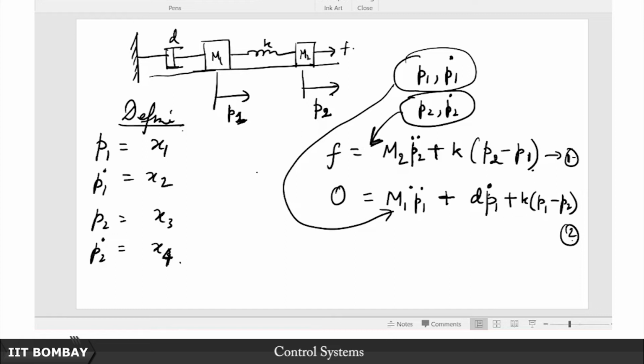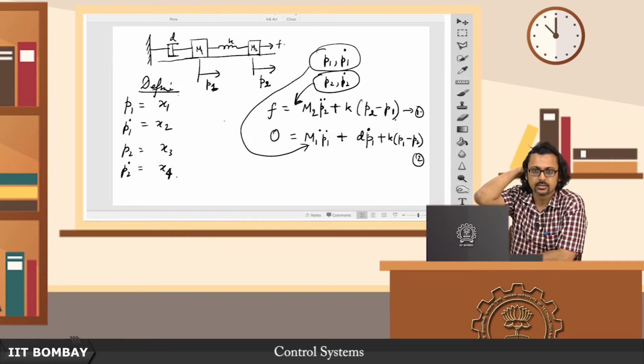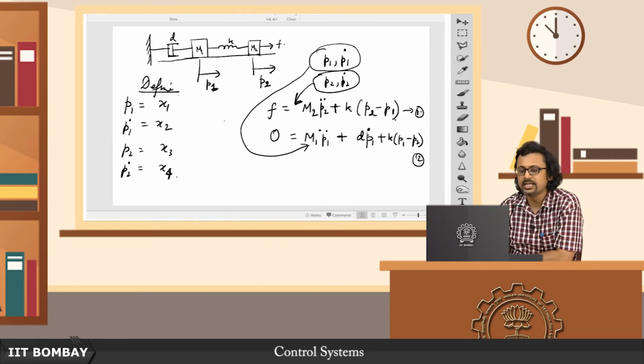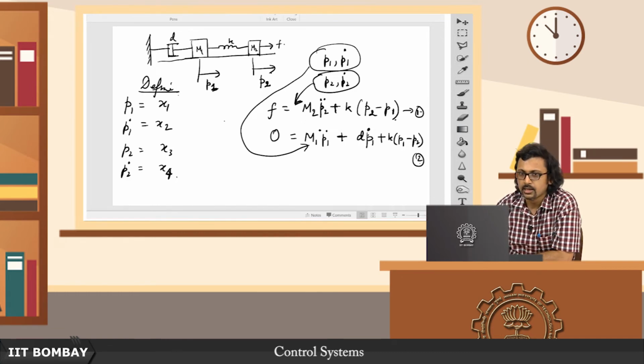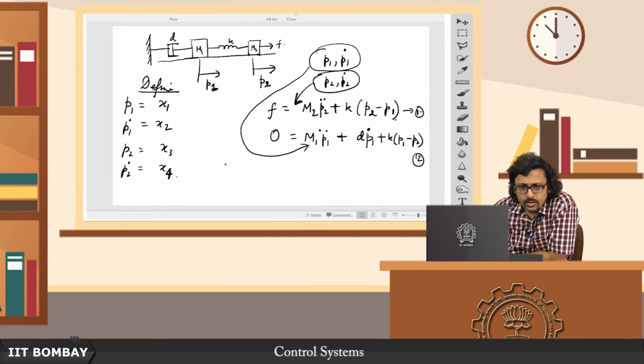So if you get a rotational mechanical system, even with gears and all, or an electromechanical system, which are systems we have seen, you should be readily able to get to their state space realizations, and be able to immediately determine how many states there will be, what the state vector will be like, and what the state space realization matrices A, B, C, D will look like in such a case.